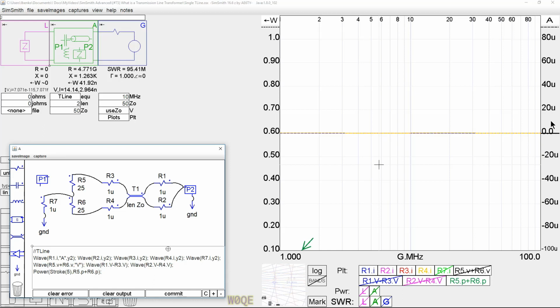Way under a microamp. So if they're way under a microamp, let's just say it doesn't matter. There are some residual small currents that flow here, and that has to do with some impedances SimSmith puts in that are kind of out of sight to the user, and they deal with making the circuit not blow up mathematically. A lot of times there are 1 gigohm resistors placed in various places, but we're talking about thousands of times less current than what's flowing normally. So let's just call that current 0 effectively.